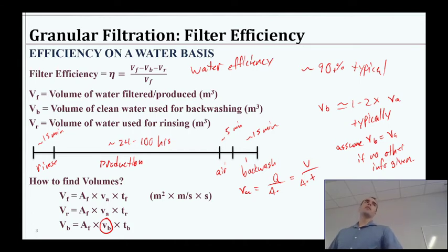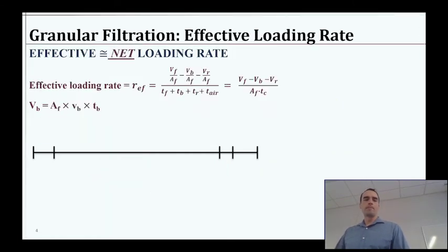If you can backwash it faster, your pumps are set up where you can do that, you might as well get the particles out of there a little quicker and be a little more disruptive to the media so that it has just that extra capability when you clean it. You'll lose a little bit more water, but hopefully you can do the process quicker, right? So it's kind of the same deal. If you had to spend more time, but you lost less water because you're not pumping it as fast, well, that's also time you're not spending filtering. So it really all boils down to whatever just makes sense for the system.